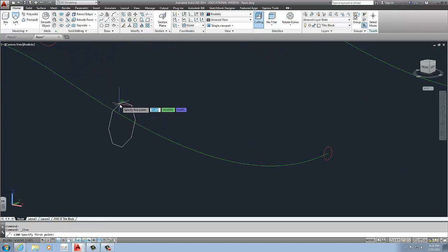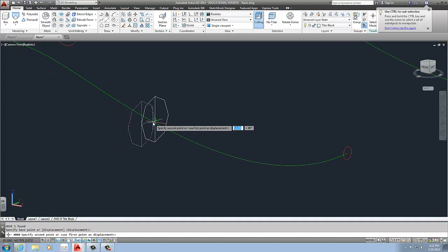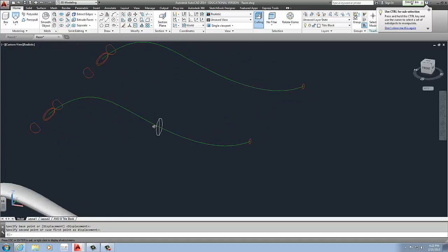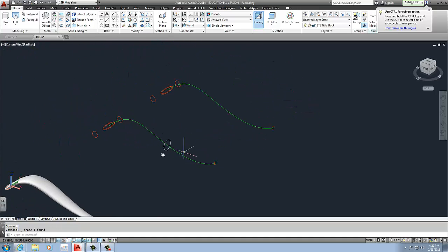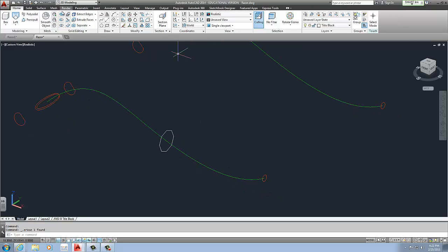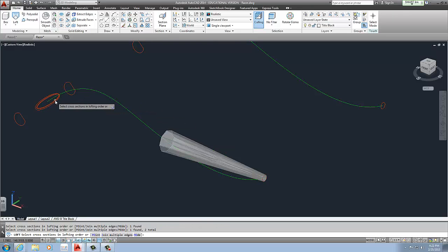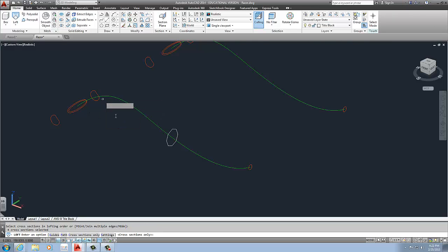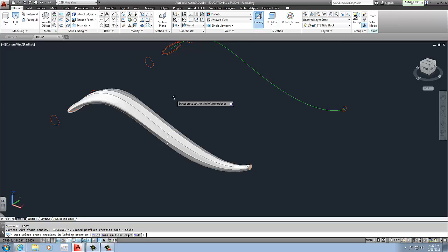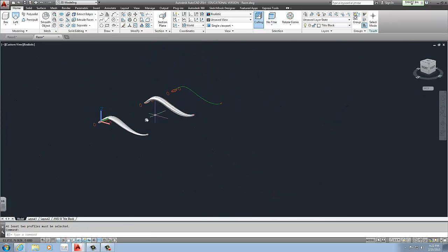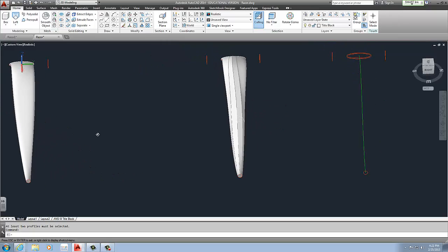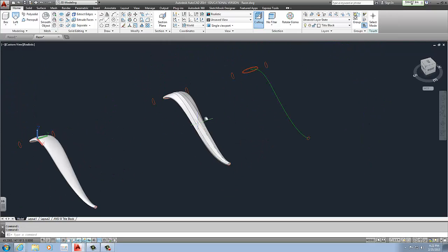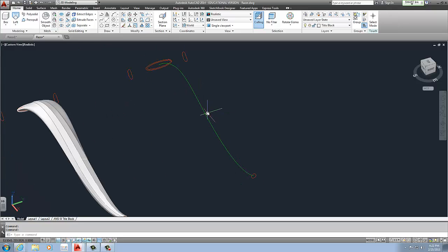If you can't get that, all you really need to do is just draw a line as a reference, and then the midpoint of that line would be the center of the hexagon. So there's my new handle design, where it's going to be lofted again from the back to that new shape, to a small shape, to the big ellipse. I click enter, type in P for path, or select path, and I create my path. So now you can see the difference in shape of my actual handle. Now you can play around with that and do it any way you please.